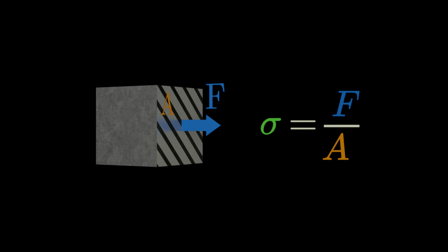If you need a refresher on stress, imagine we're applying a force to stretch a solid block. The stress is simply the force divided by the area on which it acts. A wider block will be stretched less under the same load, so by eliminating the cross-sectional area and considering stress instead of force, we can better generalize our analysis to a variety of scenarios. And much like the engineering students studying the subject, it's the stress that will ultimately cause the block to fail.